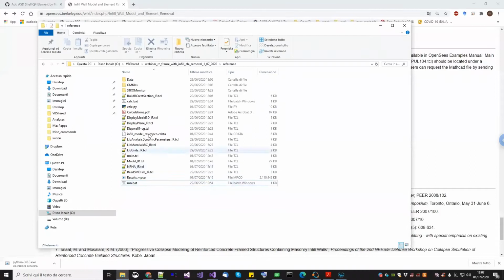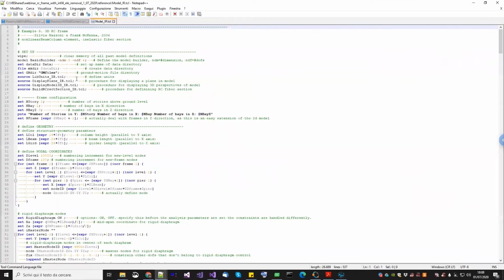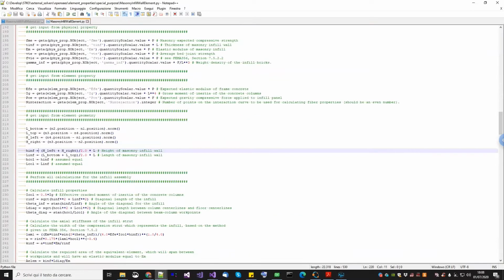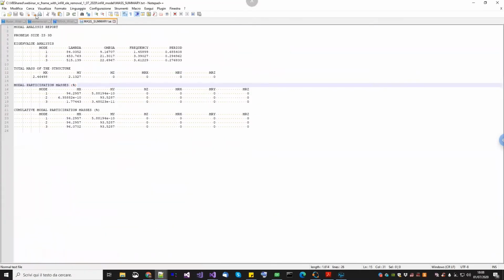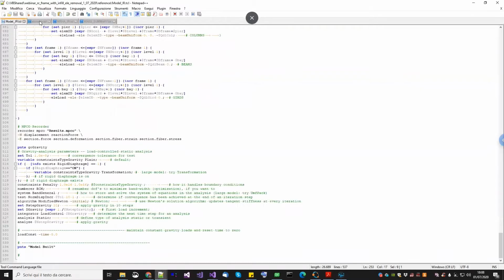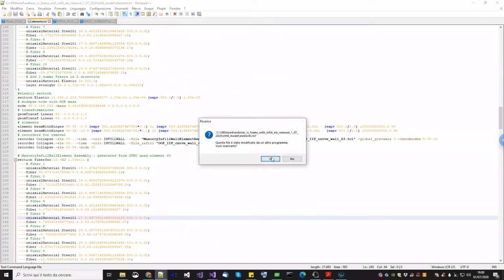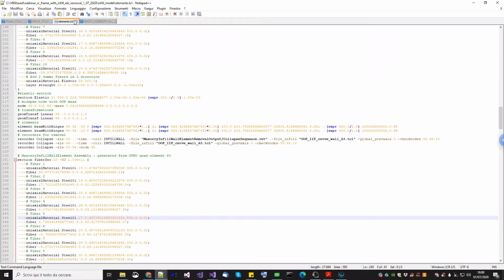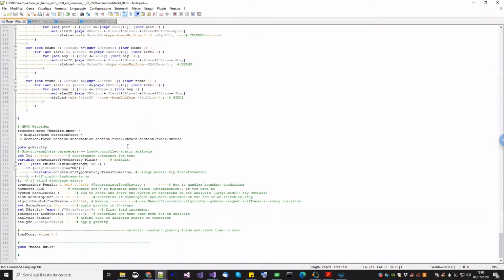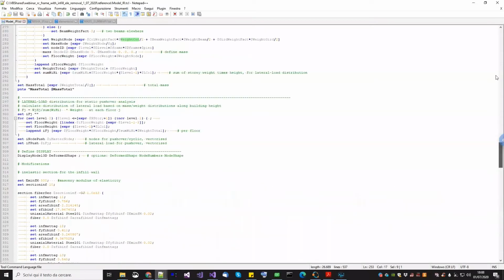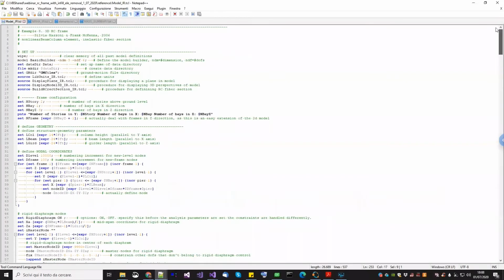And basically this is a list of files; there are many things here that are used for materials, units, so all the utilities. But the main files are two. The model.tcl, which is this one, basically builds the entire model. Actually, I already have it open here. Okay, model.tcl. Let me move this one. I will need it later on. So this is the first file that you have to source. And now I'll give you just a summary.